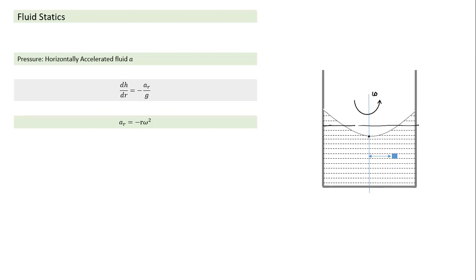It becomes a paraboloid, and so there's a lowering of level. We will not prove it here, and you don't have to prove that also. Whatever level it goes down here, a similar level it goes up here. That comes from the equation of the volume of the paraboloid property. So if we stir, then at the center it will go down by a certain height, and it will go up by a certain height here, and these two are equal from the initial level. This proof comes from the calculation of volume in 3 dimensions, which is not our scope now.